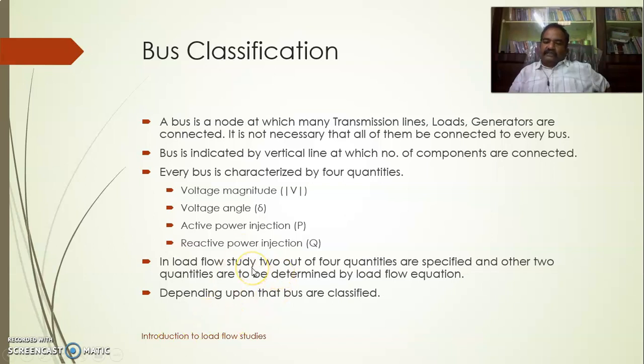In a load flow study, particularly, out of these four quantities, only two quantities will be specified, and the other two you are supposed to determine. Depending upon the variables which are available at that particular bus, the bus gets its name. Now, I'll show you.